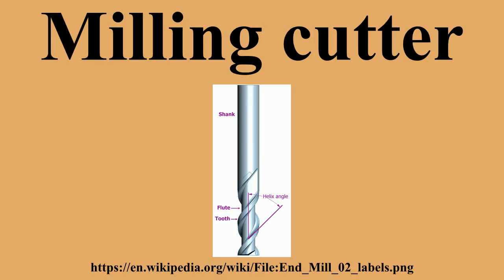The machinist needs three values, S, F and depth, when deciding how to cut a new material with a new tool. However, he will probably be given values of VC and FZ from the tool manufacturer. S and F can be calculated from them. Conventional milling versus climb milling. A milling cutter can cut in two directions, sometimes known as conventional or up, and climb or down.